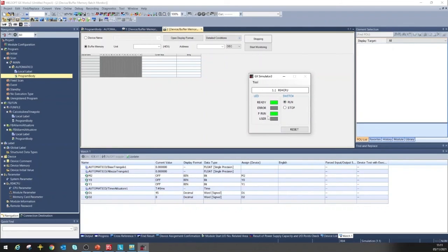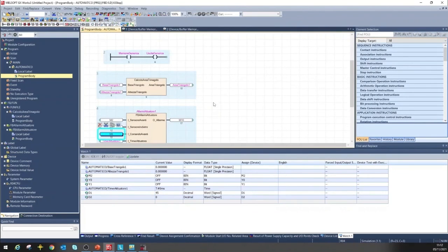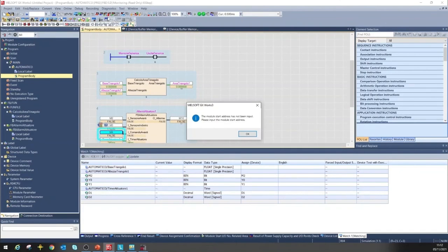The P-run LED is indicative of whether the programs are running or not. When the green LED is on P-run, it means that our programs are running. As mentioned, it isn't certain that the status of the physical run selector necessarily corresponds to run, therefore to a program running.